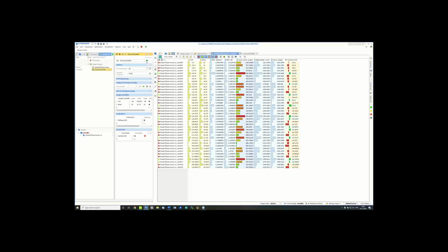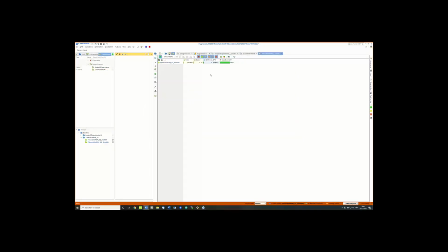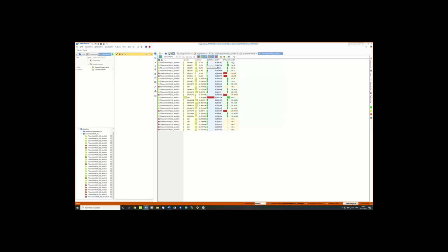And instead of evaluating CADMATIC and all the other tools, I can actually evaluate my response surface model that predicts the net present value. And if I start that simulation here, you can see in real time that the T-search will generate designs and start to converge, hopefully, towards an optimized design. We can see that we started at an NPV optimal value of 0.26 from a beam of 21.75 meters and an overall length of roughly 105 meters. And you can see over here the constraint of 150 cars from an initial 152 cars converging slowly but surely towards very close to the actual 150 cars constraint that we have had.